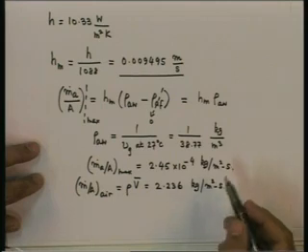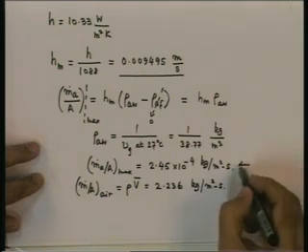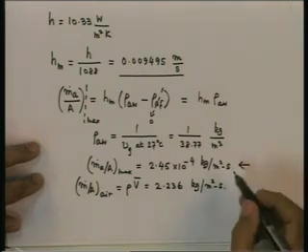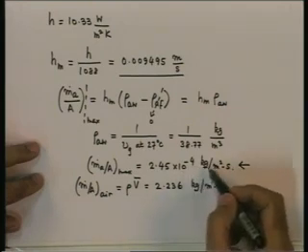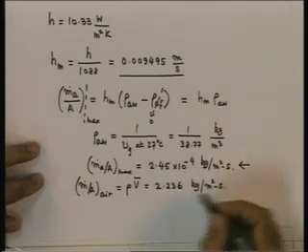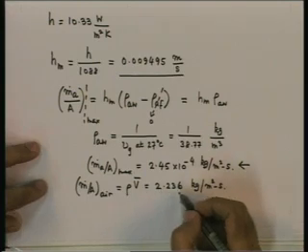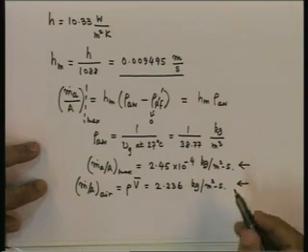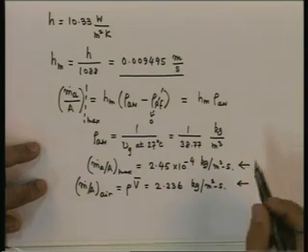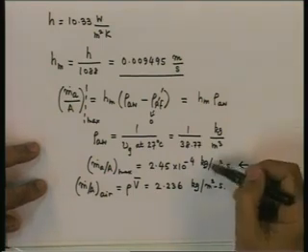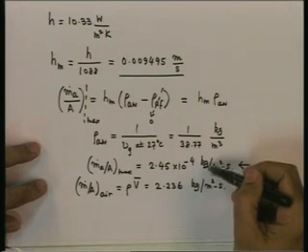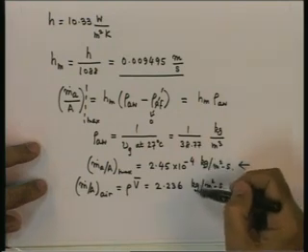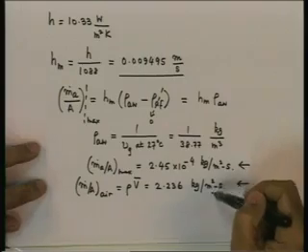So here we notice that the water vapor mass flux is of the order of 10 raised to minus 4 kg per meter squared per second, whereas that for air is a few kg per meter square per second. This indicates that the vapor mass flux is roughly 10,000 times lower than the air mass flux. This indicates that the Colburn analogy is applicable in this case.